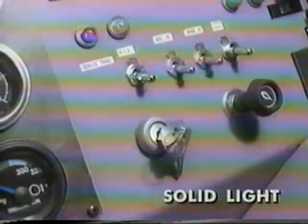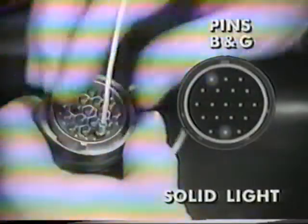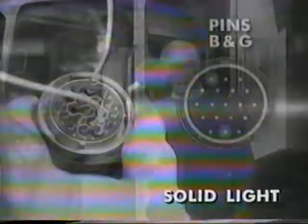First, turn the ignition switch off. Disconnect the vehicle interface harness at the shift bar cover. And use a jumper to connect pins B and G. If the light is on, there's a wiring fault in the service light circuit and it needs to be repaired.